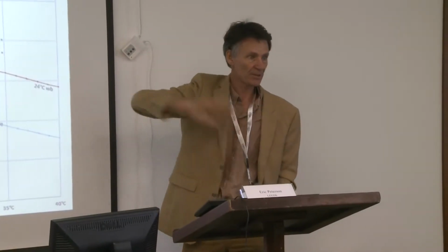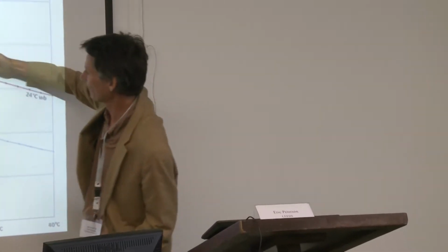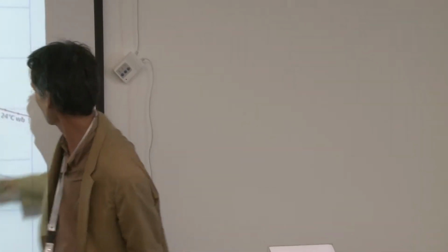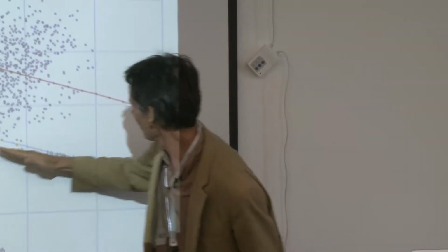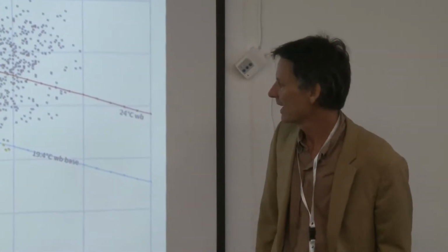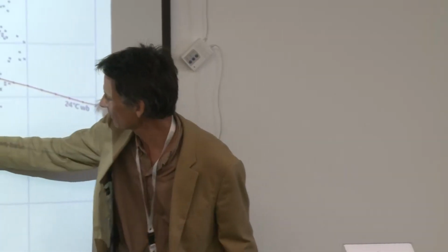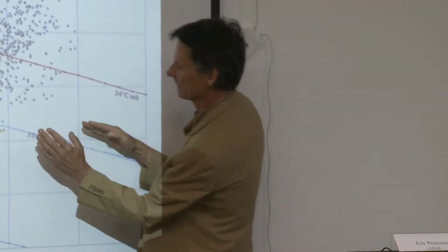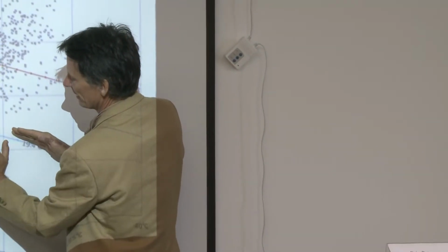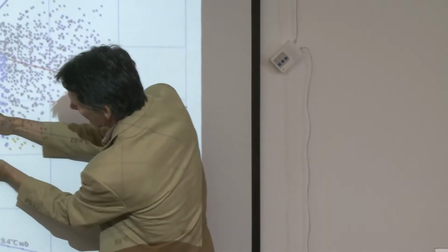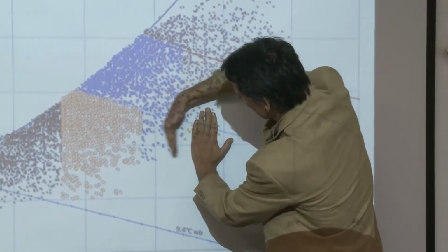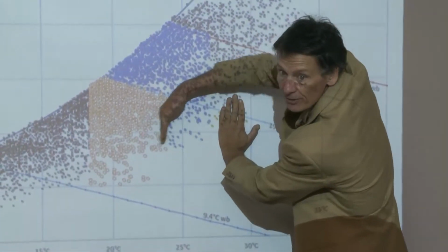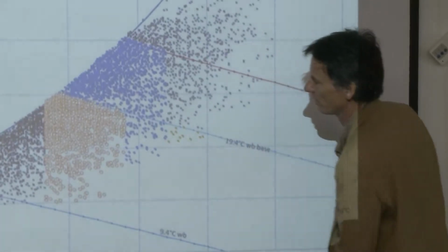Anyway, it's not in the paper, so forget about wet bulb globe temperature. Here's what I've got in my paper. I've got that 24 line, I call that the very humid temperature. You've got your normal humid temperature, 19.4. From my literature, it seems like most books that talk about evaporative cooling say direct evaporative cooling stops at that level. Now, if you could just put a swamp cooler in, you'd be good in these areas. But without a swamp cooler, in a lot of places, if you're not getting those conditions, by just having good ventilation you can push comfort this way without actually using water and a swamp cooler.